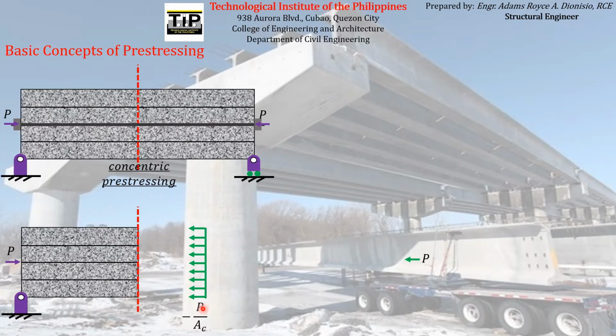Now, for example, we will take into consideration the fact that the concrete beam also carries its own weight in addition to the additional weights that it will carry, like for example, the superimposed dead load, live load, etc. So we will just call the sum of the self-weight or dead load, the superimposed dead load, and the live load simply W. That W will be carried as a uniformly distributed load by the concrete beam, therefore producing reactions here at the supports. So if we look at the free body diagram of the left segment, it will look something like this.